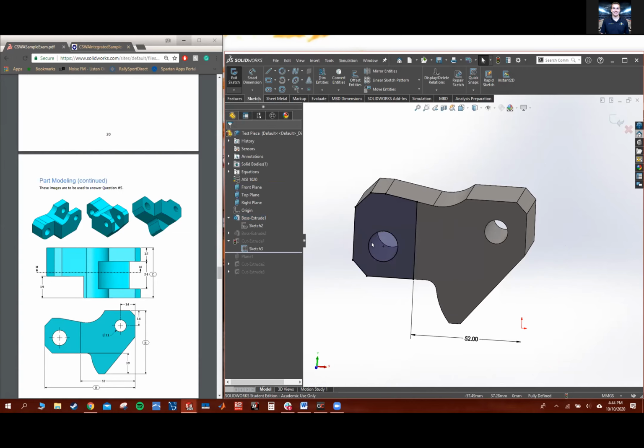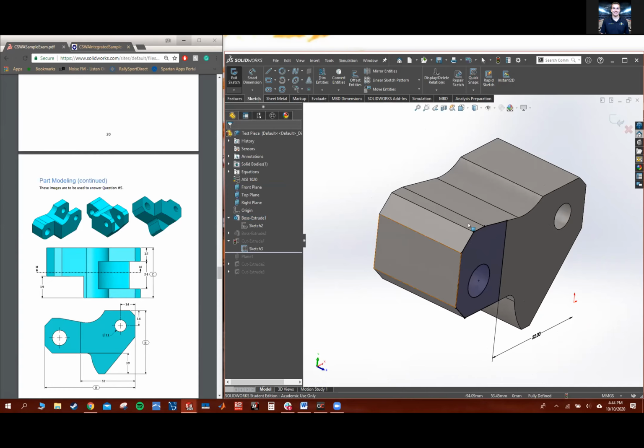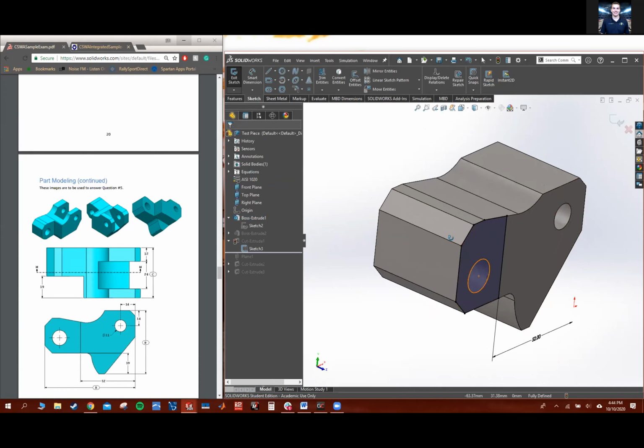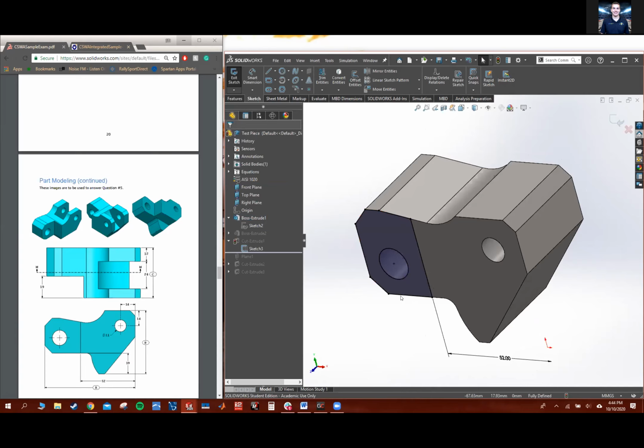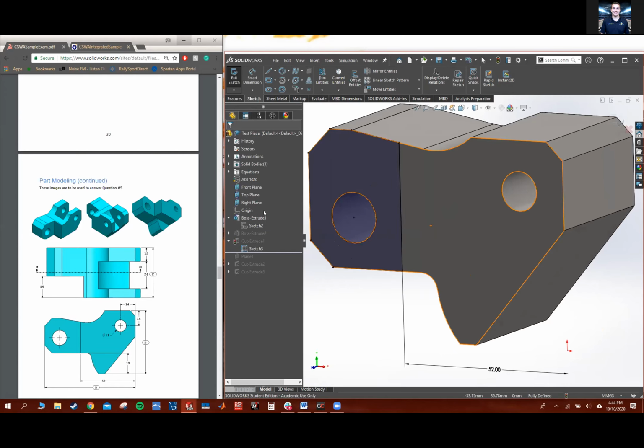So I did that. Another quick and dirty way you can do it is to actually just make a giant rectangle and then just extrude out or extrude cut however far you want to go. But then again, you're not going to be defining anything unless you set your square rectangle dimensions. So I did it this way just because it's good practice. So if this model changes, if I change the shape up here or something, it'll also change within this sketch.